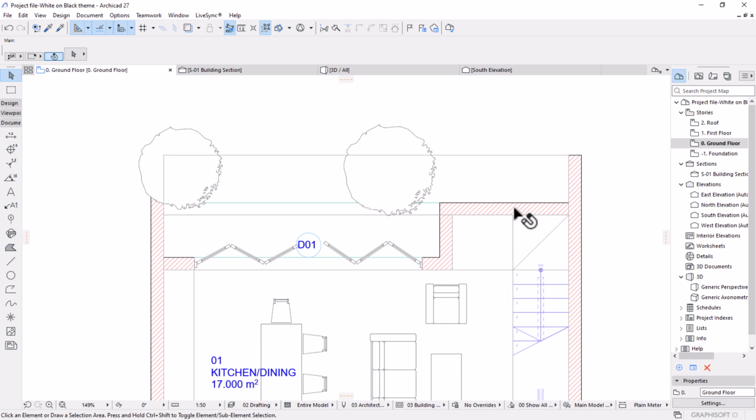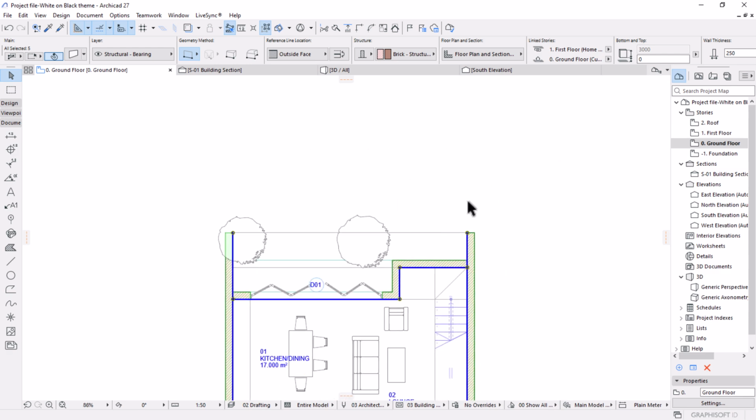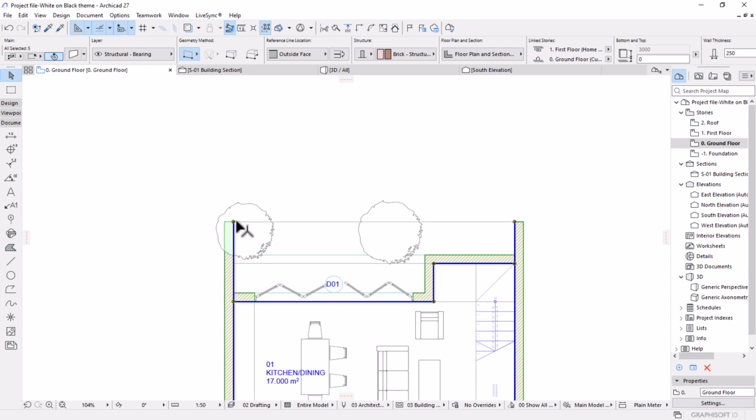So the quickest way is to select elements like walls. I'll select elements that are on the same line, for example. In this case, I want to dimension this line. So I'll pick all the elements. For example, these walls, I'm going to pick the thicknesses of it and then the positioning. For the horizontal walls, I'm going to pick the length and then the openings that are within those walls.